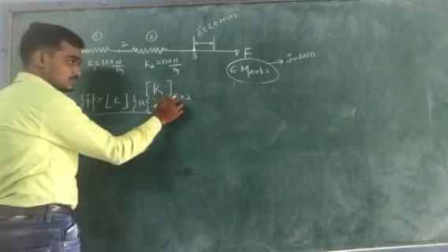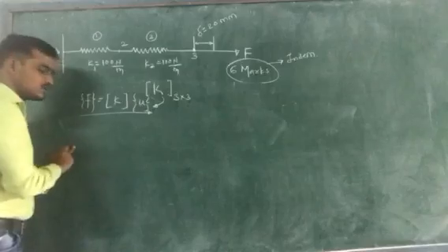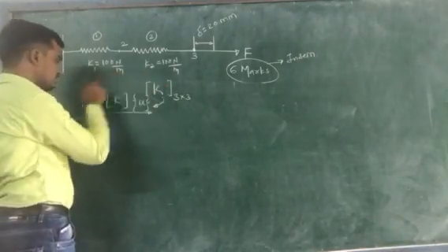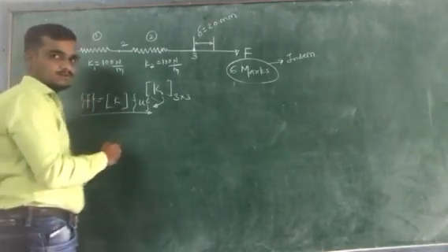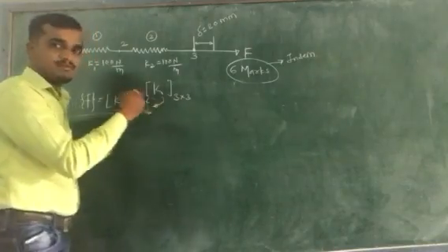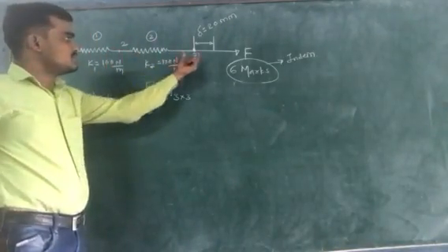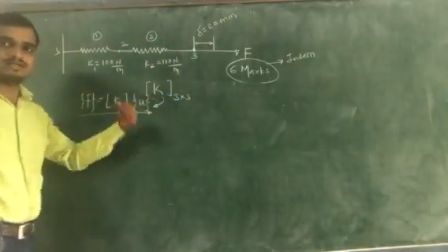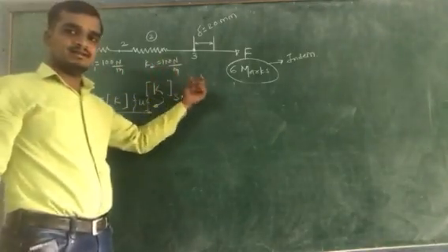As there are 3 nodes and a 3 by 3 matrix, the number of equations will be 3. By using the global stiffness matrix we write this in matrix format, so you get the 3 equations. Then apply the boundary conditions, first for nodal displacements and second for nodal forces, and then by the elimination approach we get the final answers for the displacement and finally the force.